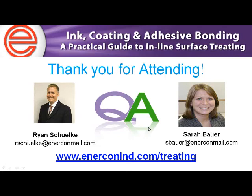Sure. Yeah, and just to piggyback on that, some of you may be familiar with contact angle. Contact angle is a measurement that's taken with a water droplet on the surface of material, and then basically you take the angle between the material that the droplet is on and the actual droplet of water. Our goal, obviously with surface treatment, is to get that water to wet out on the surface or decrease that particular angle as much as possible.